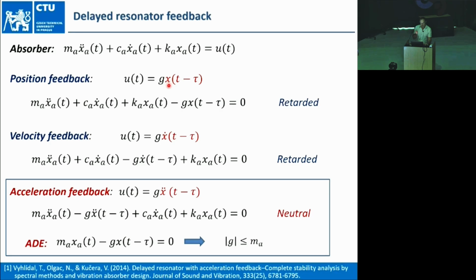So we just need a single measurement, and another advantage is that the vibration suppression is very sensitive to small system model mismatches. And if you close any loop, you always have a delay there, due to sampling or involvement of the filters in the loop. And actually, if you have a delay in your controller, you can compensate these internal delays and make it really work ideally.